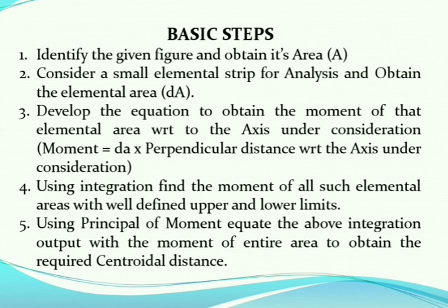Next, in the third step, develop the equation to obtain the moment of that elemental area with respect to the axis under consideration. What is moment? Moment equals dA, which is the small elemental area, into the perpendicular distance of that small elemental area with respect to the axis under consideration.